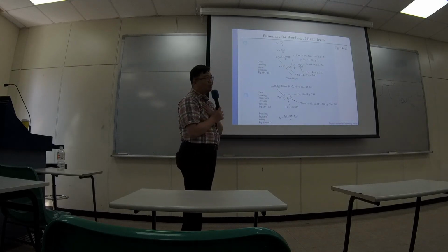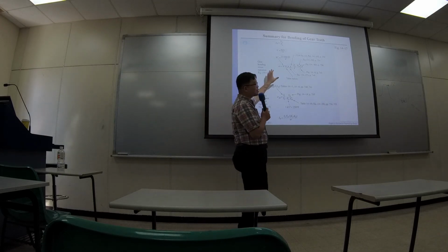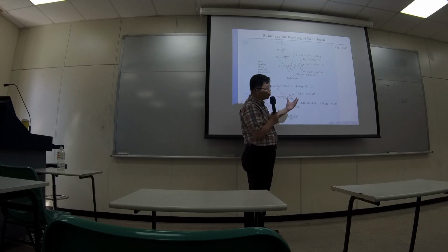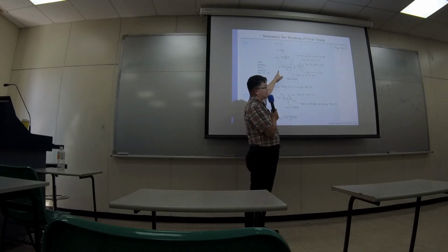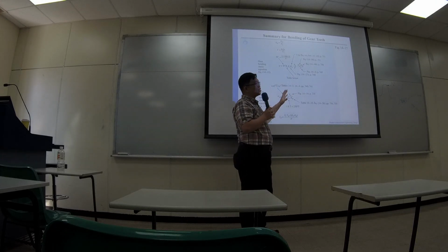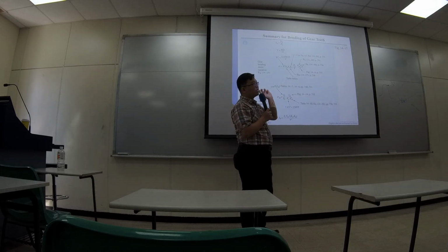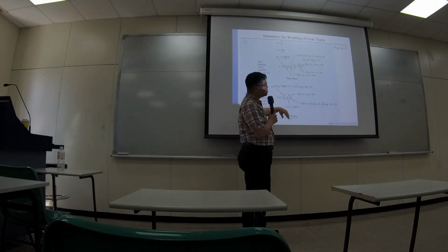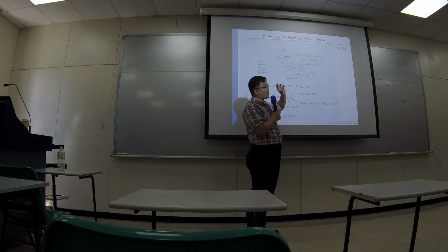My goal in teaching this chapter is not for you to memorize this. I just want to introduce you to what affects the stress inside the teeth. Everything was based on the Lewis form factor, the dimensionless parameter, and then people started to make adjustments based on different factors.